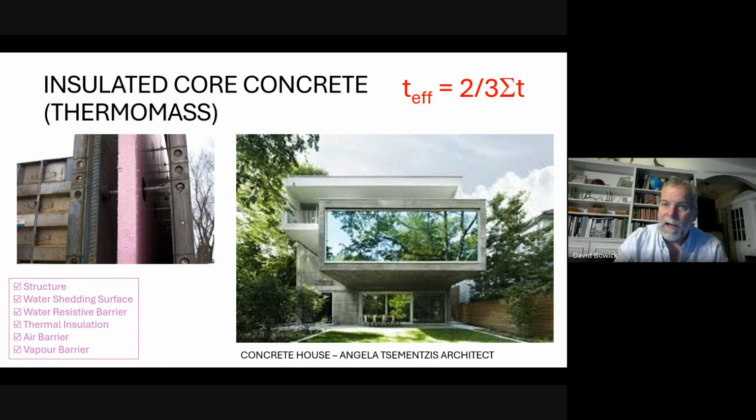And so when we're evaluating using our H/25 rule, 133 millimeters is good for just over 3 meters of height, 25 times its thickness, or 25 times the effective thickness.